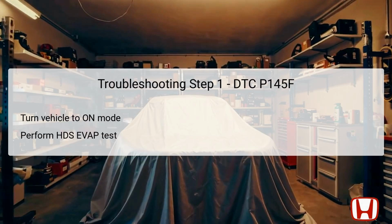The first step in troubleshooting DTC P145F involves setting the vehicle to the on mode without starting the engine. This action allows the necessary electronic systems to power up and prepares the vehicle for diagnostics. Utilizing the Honda Diagnostic System, HDS, you will perform the EVAP Leak Check Module test to assess the function of the ELCM.